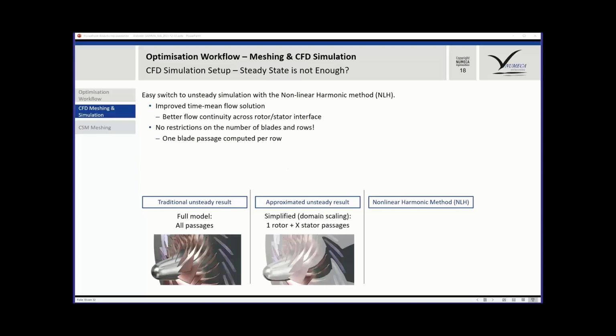When people try to take a shortcut, they find common integers between the impeller pitch and the diffuser pitch, multiplying the pitches a bit and stretching them. So that works basically the same way as a full model, but with a reduced mesh. But here, your frequencies are no longer the same because you play with the blade pitches.